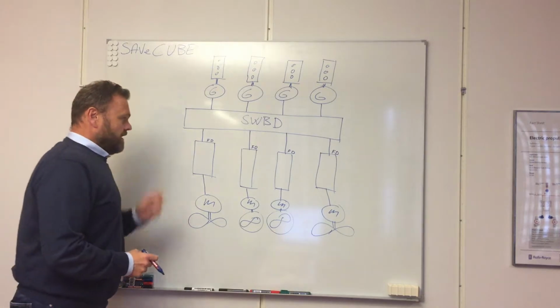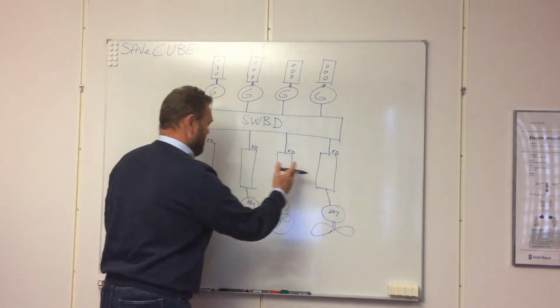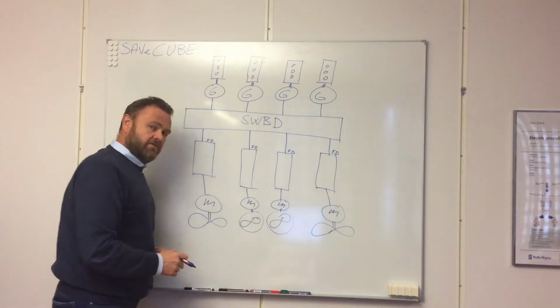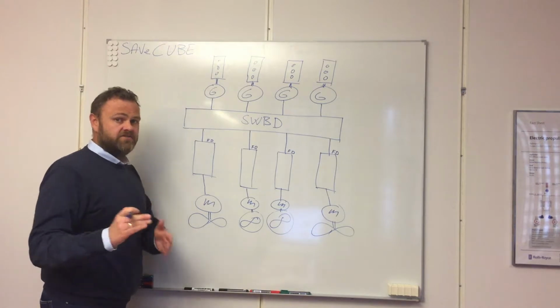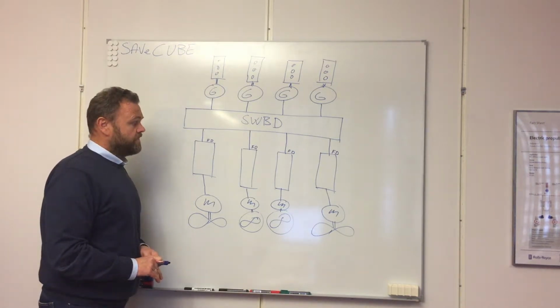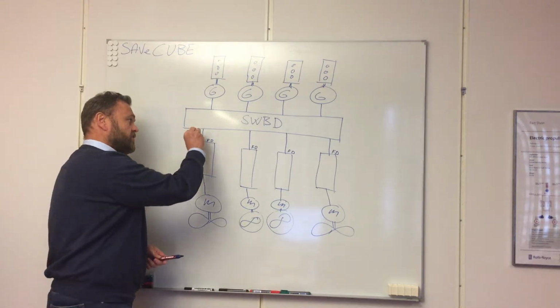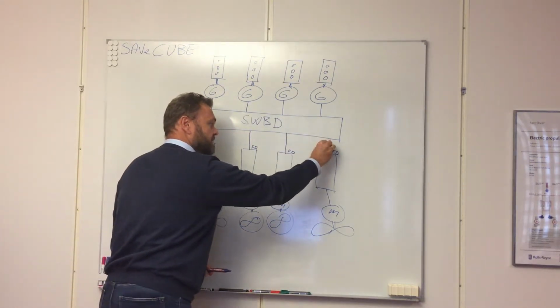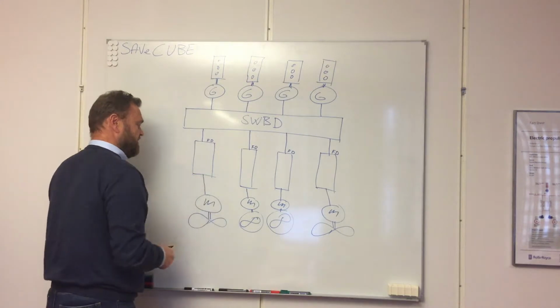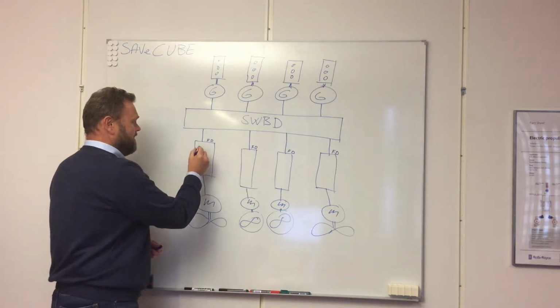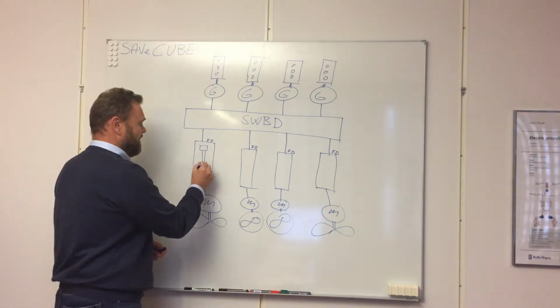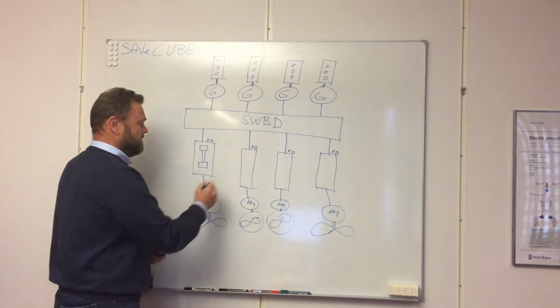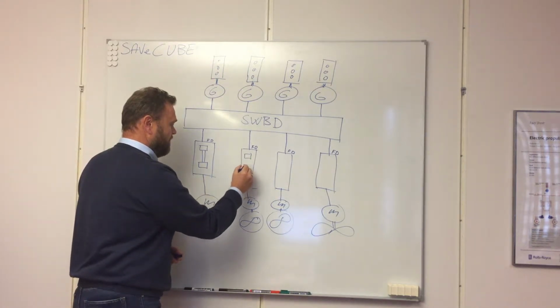So you will see that I have made 4 frequency drives based on active front-end technology, as we have touched on in another section, because I do not have any transformer in front here. Inside these frequency drives, there is a rectifier, a DC bus, and an inverter.